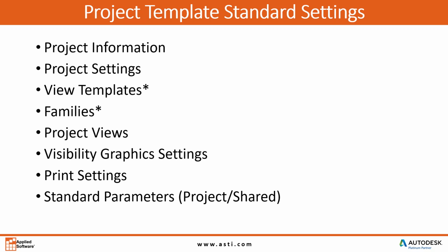So if you've gone through the trouble of creating them in project 1, all of your projects from here on out should be able to use those same view templates, so you don't ever have to go through the on-off, half-tone, change the colors for this and that and all that good stuff. You can set it up early on in a project by creating view templates and putting them in your project templates, if that's not confusing. Not all families will transfer over or should be in your templates. And when we use the transfer project standards, not all families will transfer into a project from a template.